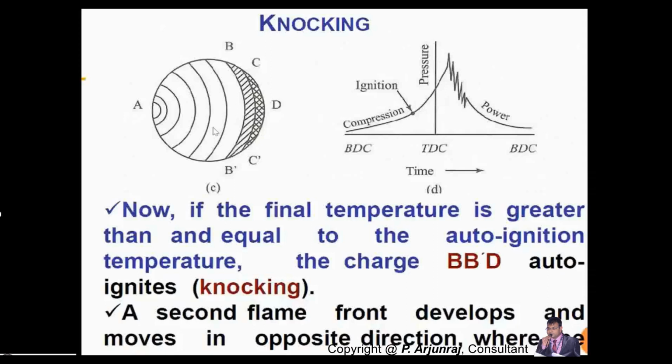When the piston moves from BDC to TDC, say for example, the ignition should happen 50 degrees before TDC. But instead of 50 degrees before TDC, there is a possibility that even when the piston is at half the position, or at 40 percent of the position, the spark will ignite well in advance.